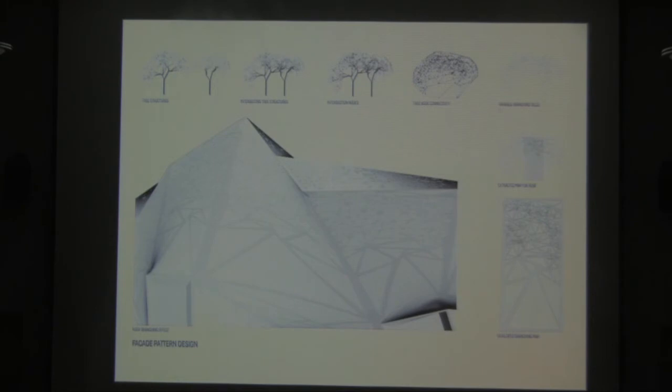And the joints of that skin have to be panelized. So we wanted to kind of keep this motif of the tree and have this kind of structural pattern, which we're looking at branching patterns generated through Grasshopper and mapping those against our mesh and using them to create an irregular pattern which has a reference towards the tree but is not literally a tree.